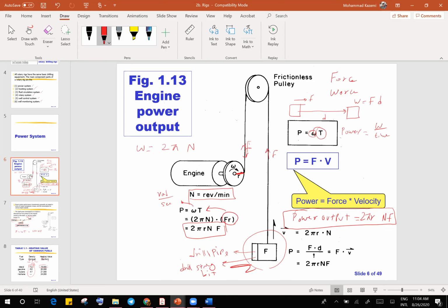Yeah, drill pipe, which we basically call stands, right? The stands are 3 joints of those drill pipes. For example, 3 drill pipes attached together is a stand, or they call it a drill stand. The length is usually 90 feet. There are many of those stands depending on the depth of the wellbore that we are drilling, right?